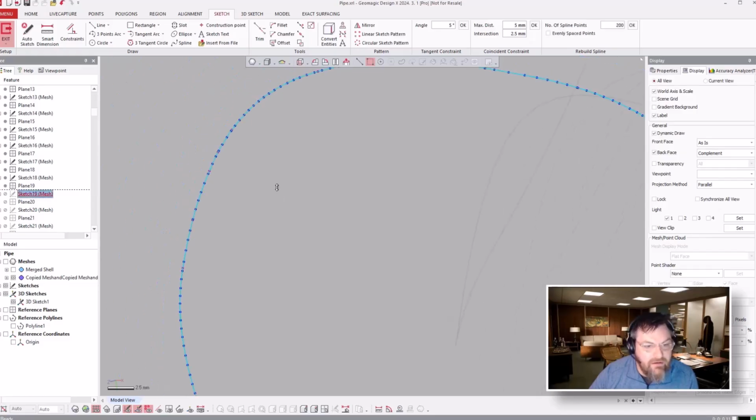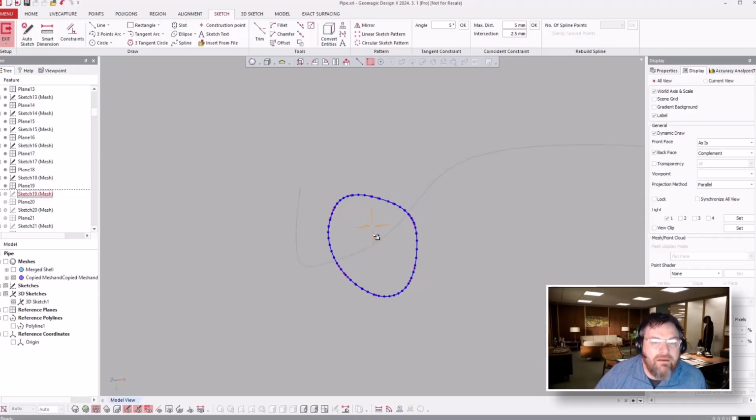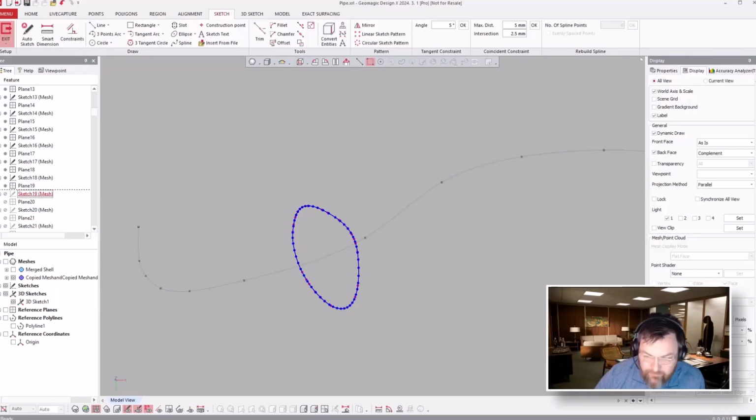And here's another piece of functionality that I'll highlight while we're in here, which is the spline nodes. You'll see that it has 200 nodes. So you can click on that and say, I want to do like 50 and then reduce it down. Anybody who's done a lot of lofting knows that if we're going to loft these profiles together, and this one has 10 nodes and that one has 200, you're going to create a really crazy looking wrinkly loft or sweep if you have profiles that are crazy here.